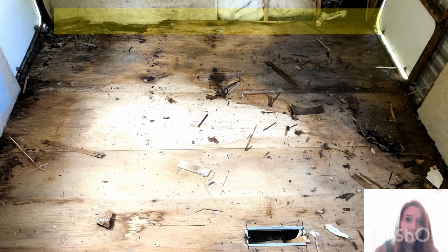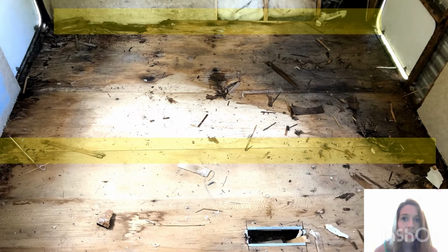Now the first thing I do is look for that 4-foot seam because I like to work in 4x8 sections. So relative to where the water damage is, in this case, it makes the most sense for me to remove the whole 4x8 section and then trim off the excess rot towards the walls. So if you see the yellow that just popped up, there's a line going down the middle of the floor there. That is my 4-foot section. So I ended up removing all of that.